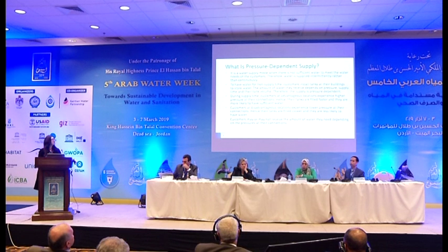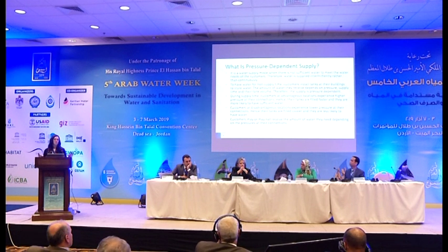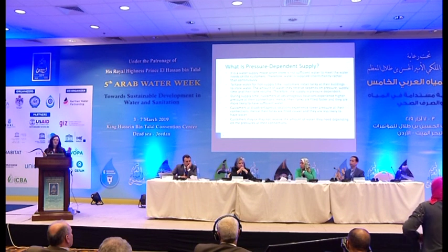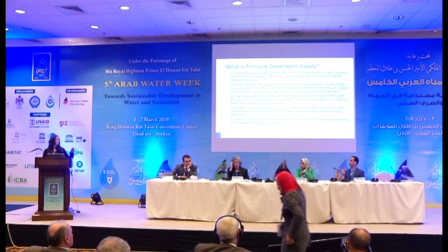So what is pressure-dependent supply? Most of the models developed in this region are hydraulic models based on demand-driven models, where the customer's needed supply is simulated as a constant demand at the customer connection point.